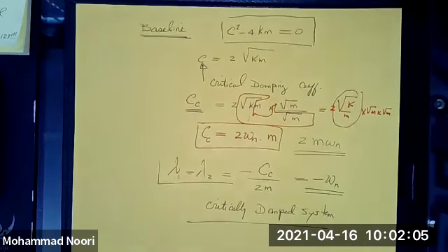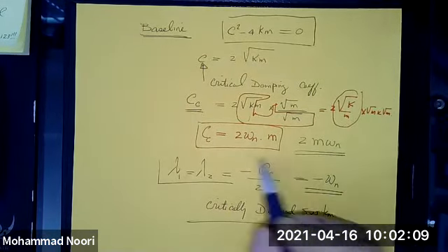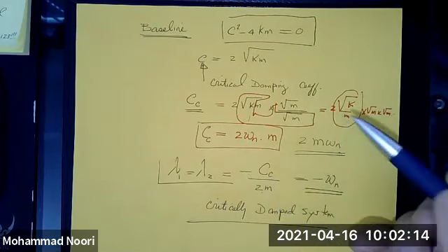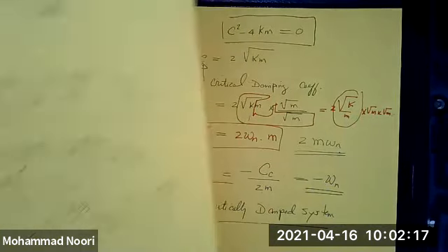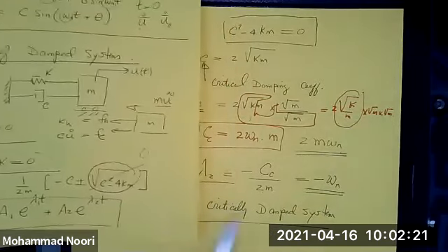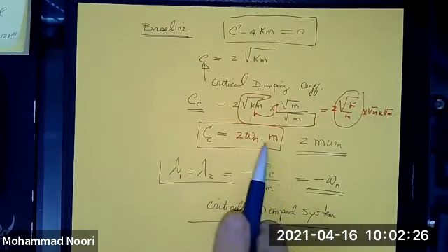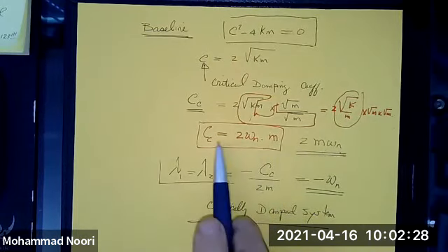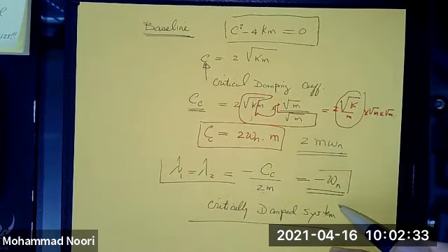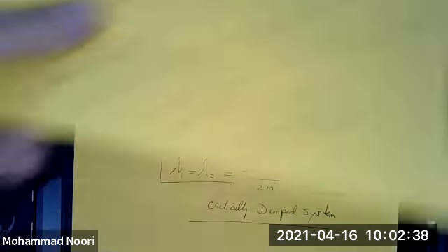Here we go. So when that's the value of the damping, the two roots become equal and it's critical. Obviously from here, if this is 0, you see that the two roots would be minus C over 2m. C in this case is the critical damping. So the two roots are equal to negative of natural frequency. And we call this the case of a critically damped system.